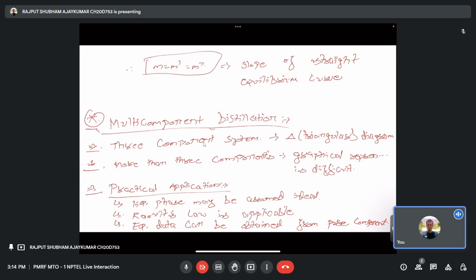The equilibrium relationships are more complex for multi-component systems. In particular, the identity of the most volatile component may change with the temperature in the system. Equilibrium data is necessary, or can be used, to calculate the multi-component bubble points and dew points. The limiting cases of total reflux and infinite reflux apply to multi-component columns just as to binary systems. So it's similar to the binary system.